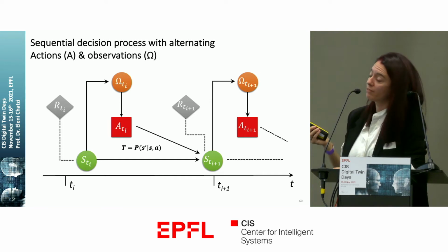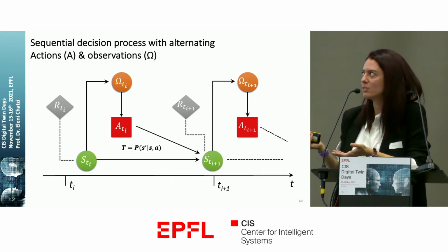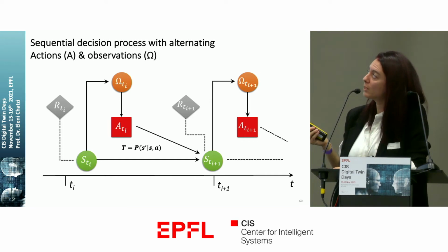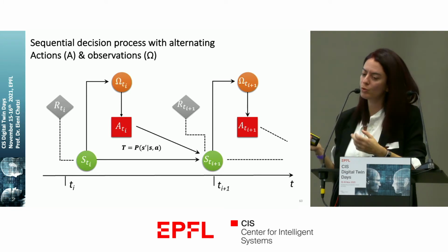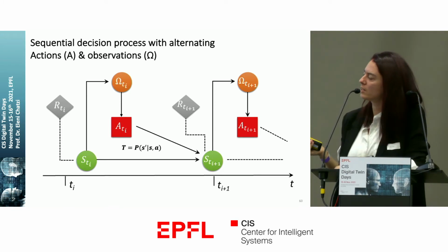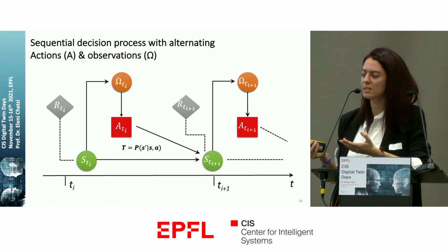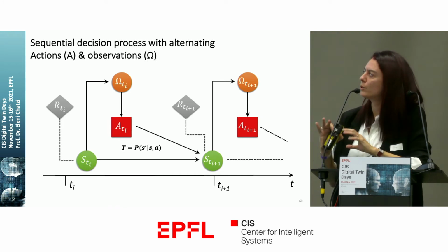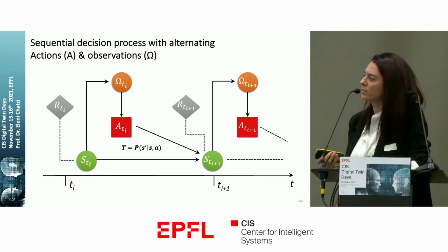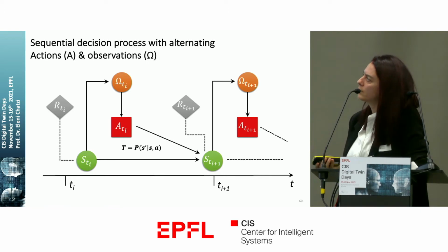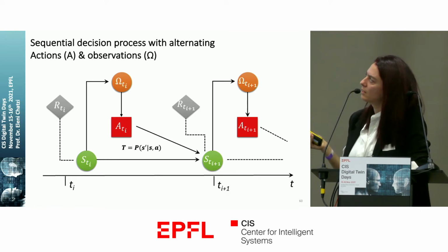You have a set of observations that you could take. Maybe it's monitoring, and so it's continuous information, or maybe it's more specific actions, like a visual inspection you need to do, or a non-destructive evaluation that's more expensive and specific. And then some actions on what you need to do with your system. For the railway, maybe it's a minor action, like tamping, which is basically a local replacement of the infrastructure, or a complete renewal of the system. And everything comes at a cost.